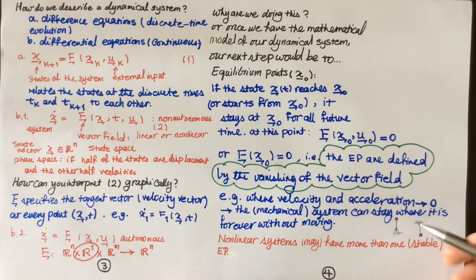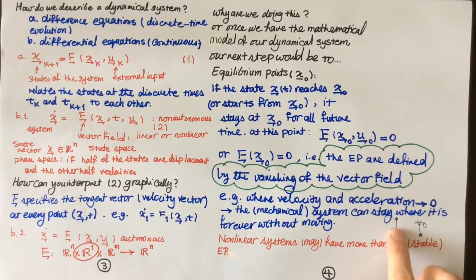This is exactly vertical along the line of the gravitational force. So the gravitational force, which points down, if you write down your equation of motion using Euler's equation of motion about this point O, for example, sigma M, the net moment about this point, goes to 0. So your angular acceleration goes to 0, angular velocity goes to 0, and as long as all the initial conditions are equal to 0, this pendulum is going to stay at this position.